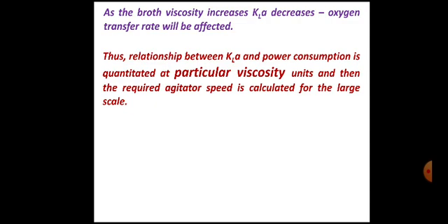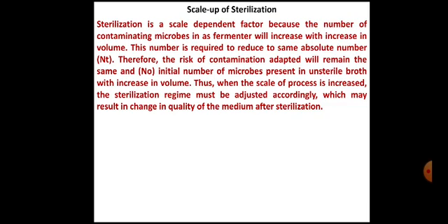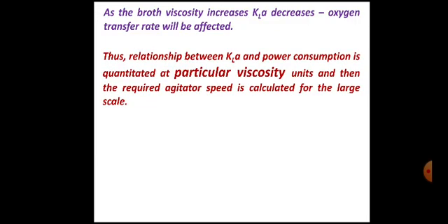So KLA has to be determined considering the viscosity of broth, considering the factors which are responsible for modification of rheological properties of broth, the factors we have seen in the last slide. This is how the scale up of broth rheological characteristics is done. In the scale up process, broth rheology plays a very important role during the fermentation process.